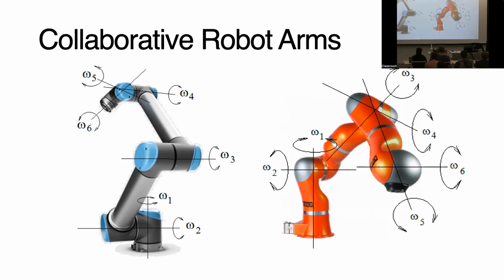But really, the joints tend to have sensors that allow the robot to detect when forces are outside of what they would expect for moving, like it hits someone and the forces go up because it's hitting an obstacle, and that way it can stop and correct and not harm the person that it's working with. So it's allowed to be collaborative.